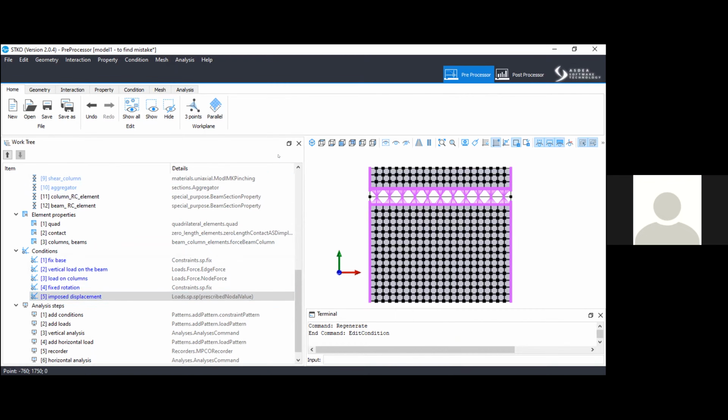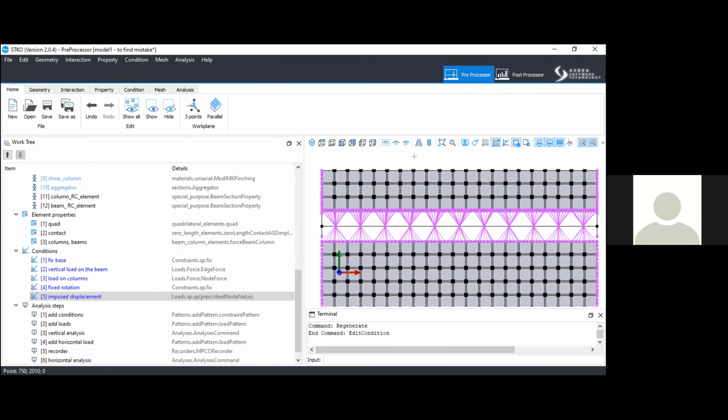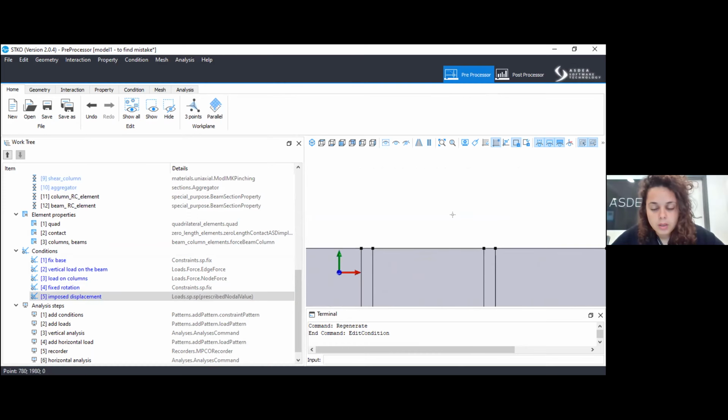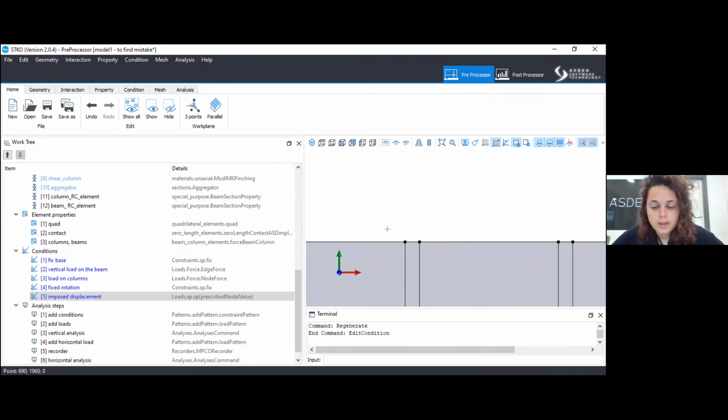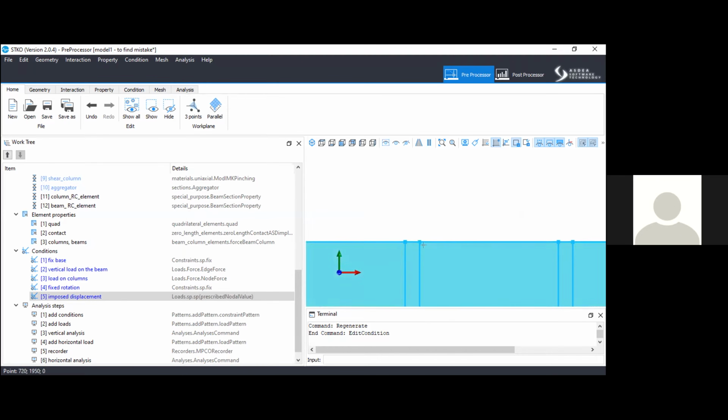Then if you don't have an extra geometry, I don't know what that interaction is connecting with what. What did you put as master and what did you put as slaves? I put as master the left node, the first one, and all others I put as slaves. The idea was that if, for example, we applied horizontal load just to one node on the left, all nodes would react the same.